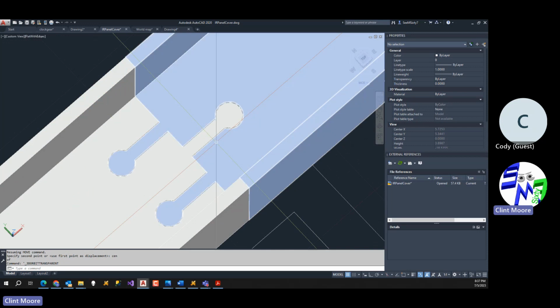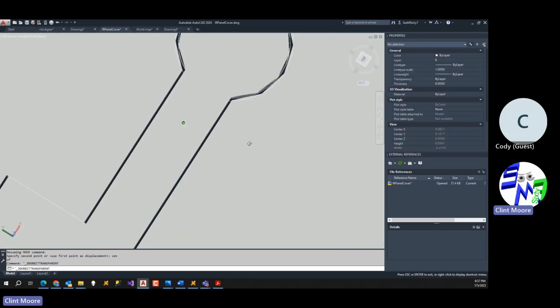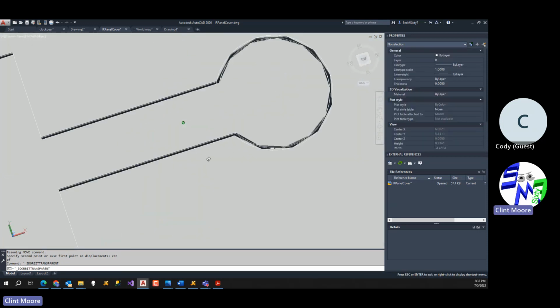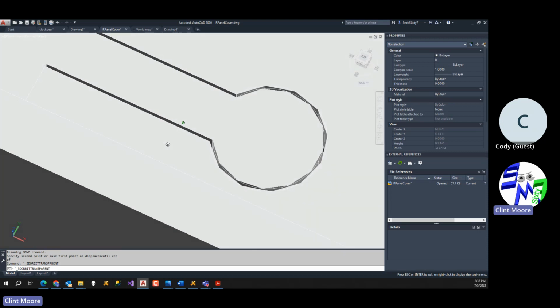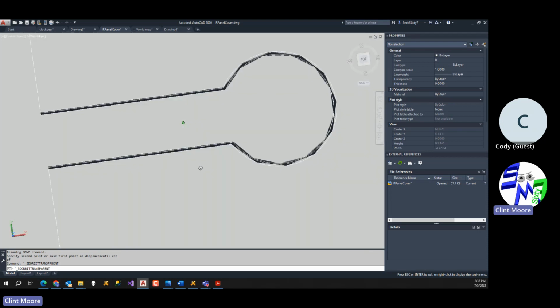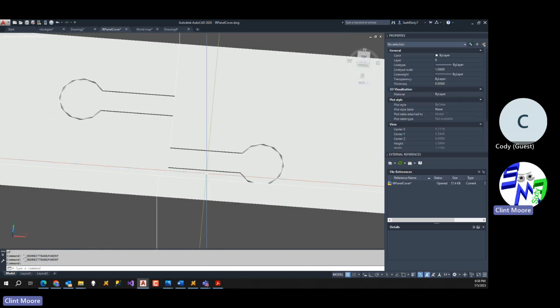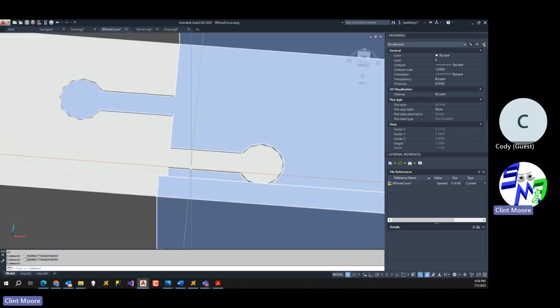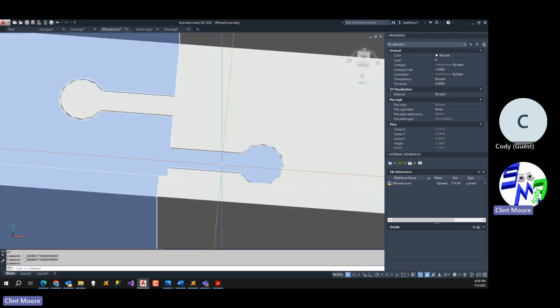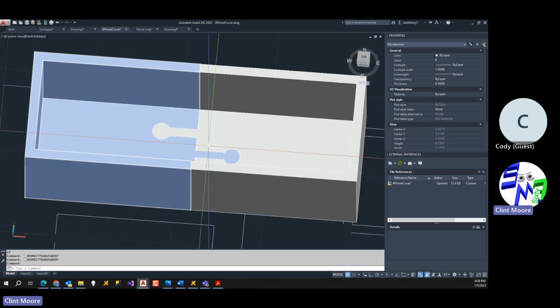When you are doing things like this, you definitely want to have a gap in there. Notice there's a gap. Mine actually ended up being a little bit too big. Depends on the accuracy or the tightness of what you're printing. I have mine printing at a decent detail level, so it's not as snug as I want it to be. If I'd have made this a little bit thicker, they would have actually kind of compressed together and stayed a lot better.